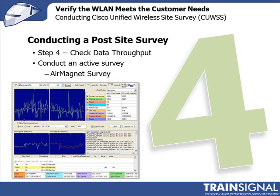So just to remind you, a passive survey is when you're passively listening, and that gives you things like the signal strength, channel allocation, noise level, signal to noise ratio, etc. In an active survey, you will associate with the access point and actually send data frames backwards and forwards. Now, the Cisco Spectrum Expert is for a passive site survey. You can use the AirMagnet Survey tool both in a passive and an active mode.